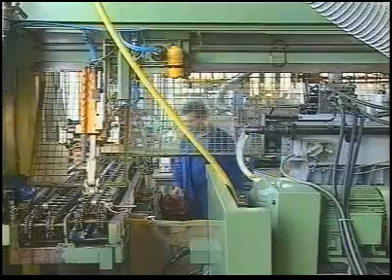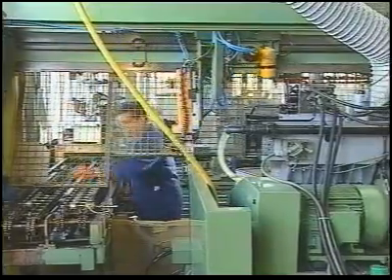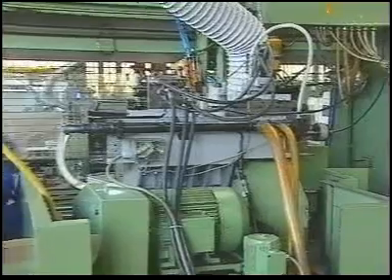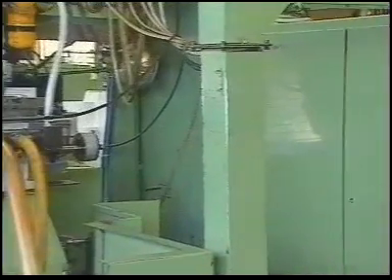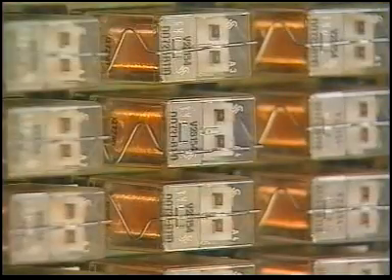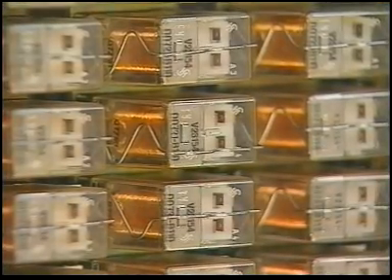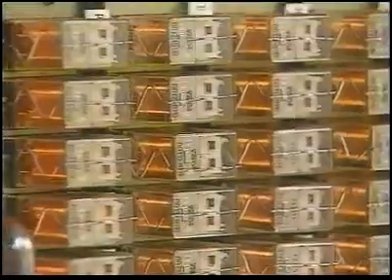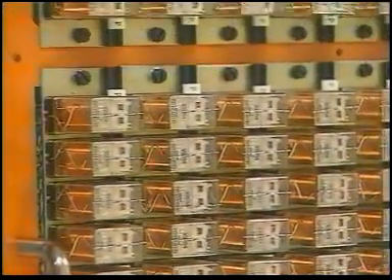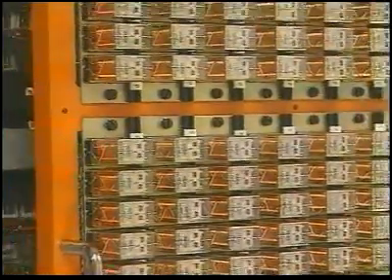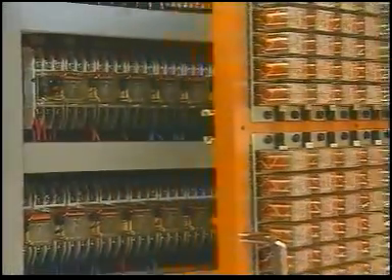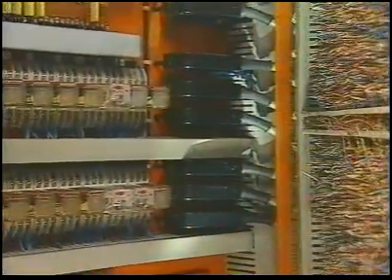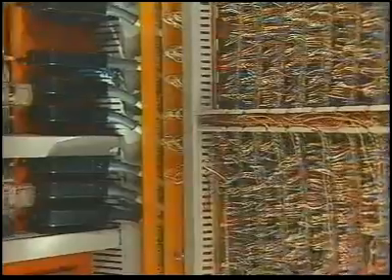Wired controllers are systems in which the sequence and the functions are determined by appropriate fixed wiring of the individual elements of the control part. Electrical lines are primarily conductors for electric current, but the arrangement of the various elements and the way they are connected determines the function of the system. Changing the program sequence requires a change to the wiring.